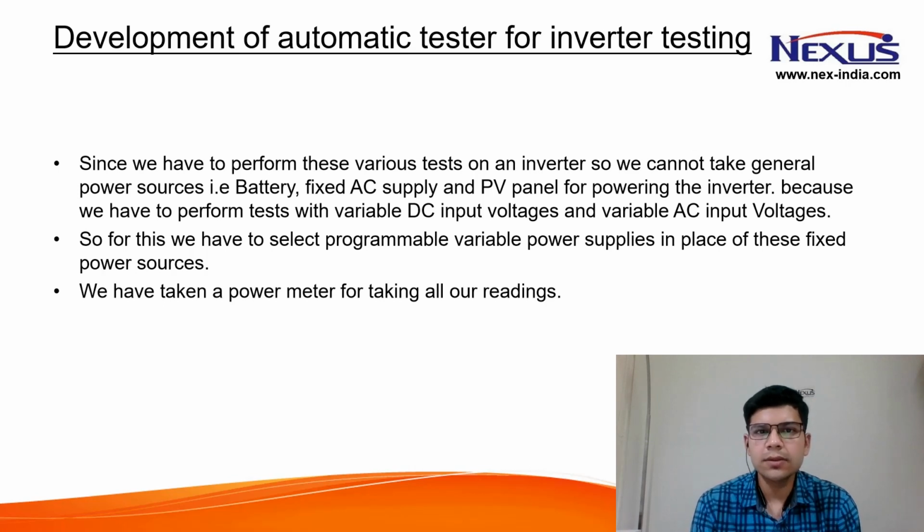So for performing all these tests, what we have done is we have simulated these general power sources. We have simulated the DC battery power supply, and we have simulated the solar power supply of PV panels with the help of programmable DC power supplies. And for simulating the AC input supply, we have taken programmable variable AC power supplies. And we have taken a power meter for taking all our readings.